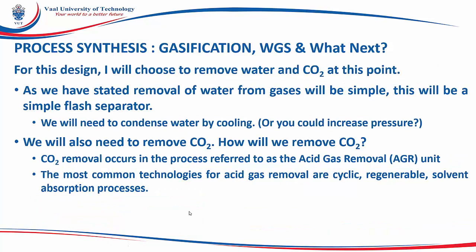For this design, at this point, I will choose to remove the water and CO2. As we have stated, the removal of water from gases will be simple. It will be a simple flash separator. We will need to condense the water by cooling. That's not too complicated. Or you could choose to increase the pressure, because higher pressure also will condense the water, but I think cooling will be a better option.